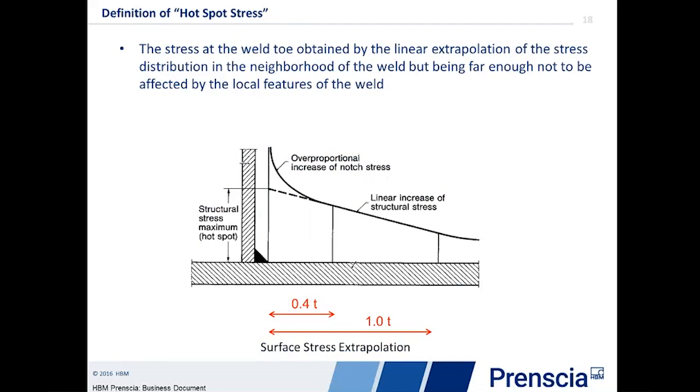This is used by quite a few weld design codes. It is relatively labor-intensive to do in FE, because I would need specific stress recovery locations, typically at the locations that I'm sampling. And again, it's only going to give us stresses at the weld toe. It doesn't tell us exactly what caused the stress, which you'll see is important later.